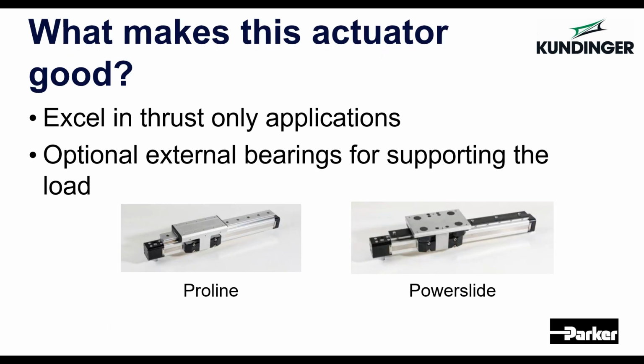Start off with the OSPE-B, which is a standard belt drive with glider bushings and by far our most price competitive actuator. Very low precision when you don't need any kind of precision, low to medium load, medium to high speeds, being that it is a belt. Holds up well in industrial environments too, just due to a glider bushing and an IP54 rating with that strip seal on top.